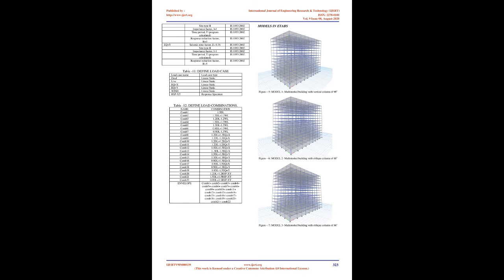To study the same floor area of the building with different angles of inclination of oblique columns. To determine the effect of wind load and earthquake force on various parameters like story drifts and lateral displacements in the building. To define the most efficient angle of inclination in high-rise buildings which can provide the most effective wind load and earthquake force resistant capacity by observing the comparative studies. To model a high-rise structure in ETABS software.